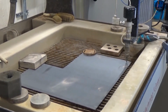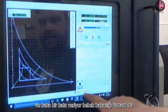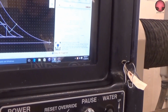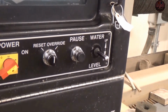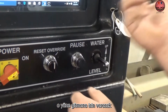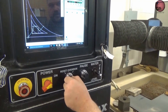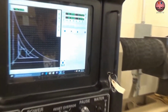Okay, and it just stopped on me because it actually went too far, and it's giving me an error, babysit. Anytime this happens, there's a switch on the control board called reset override. Now you want to be very careful whenever you're turning this. It'll let you keep going that direction. So whenever you're turning this, let me close this real quick. Turn this, and I'm going to right click on jog left.